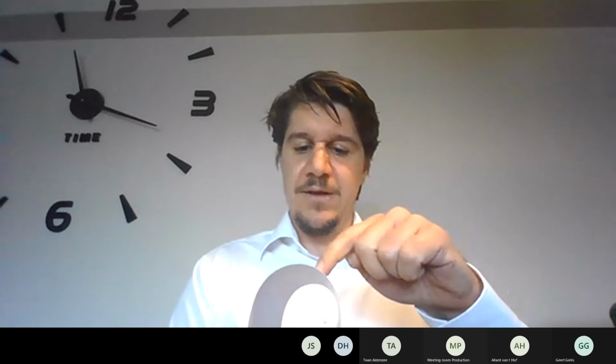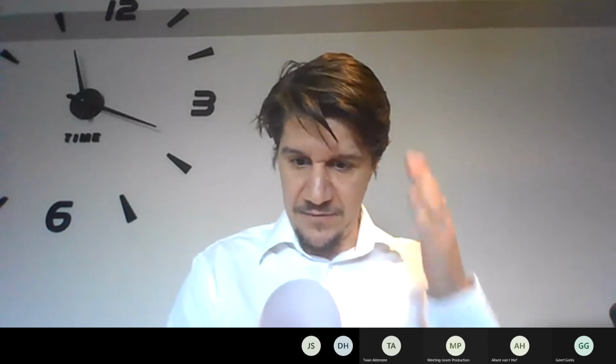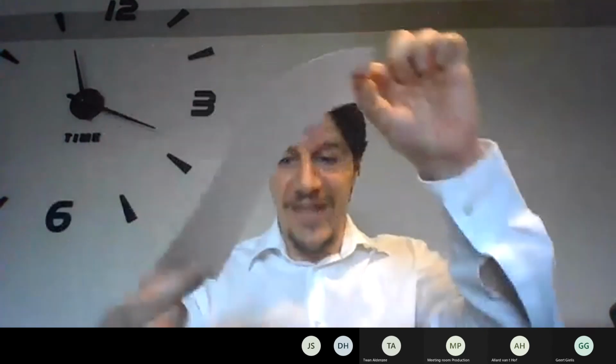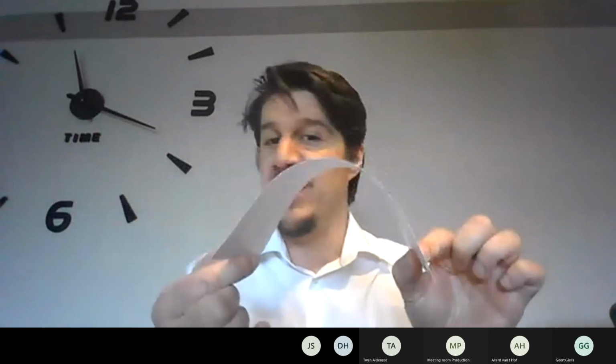What we are doing here, we don't move the head in Z at all. The pad is here. Here also, like always, we just look at the perfect angle from the top. And now the pad is here, we just move the angle of the board with the conveyors. So we take the board and we move it. For sure it's not like that. If you have a warpage like that, then you have other problems.